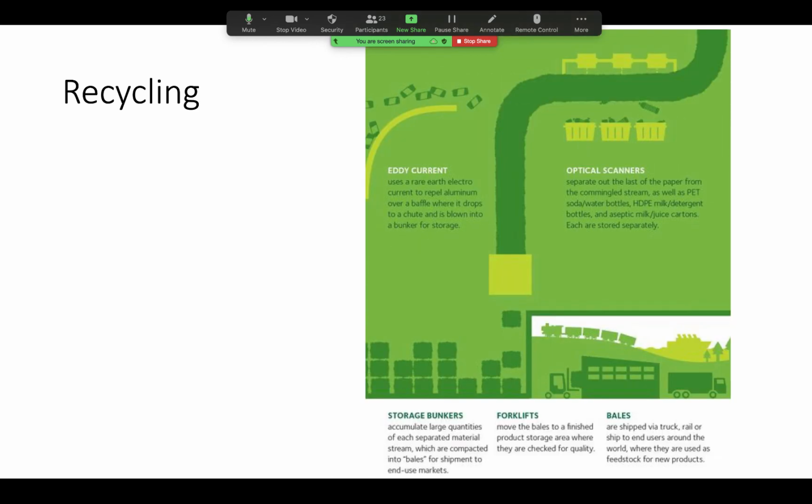And then you get rid of your aluminum, and then you're left with all your plastics. Then your plastics are all kind of put here together. And this is where you need to be able to sort out the things that are actually recyclable and things that aren't. And sometimes in this place, you're going to wind up with a lower quality plastic because the plastic is going to be dirty, or it's going to have contaminants from some other materials. And in this way, they call it upcycling versus downcycling. So some materials can be readily turned right back into it. If we have just some polypropylene and it's going to go right into some polypropylene pellets, you can put it right back into your molding machine and make more material like nothing happened.